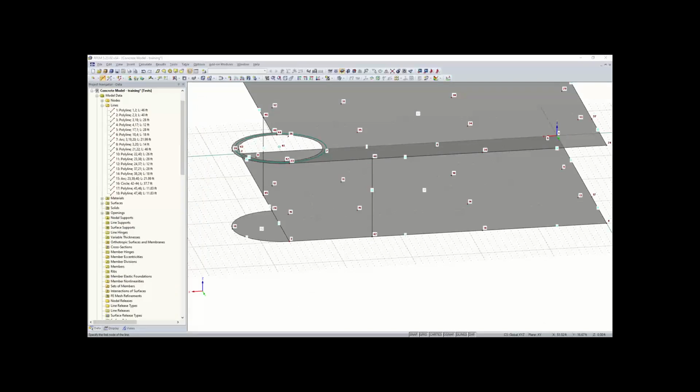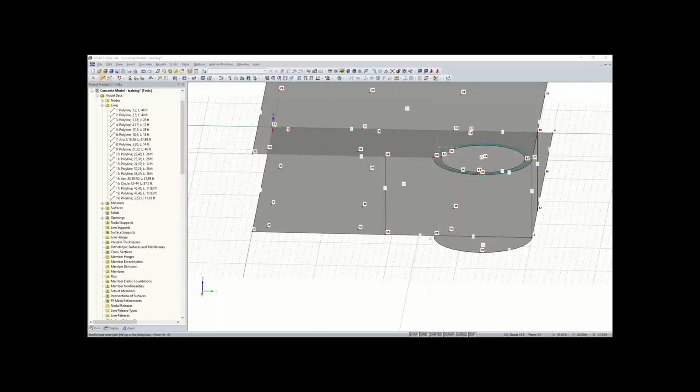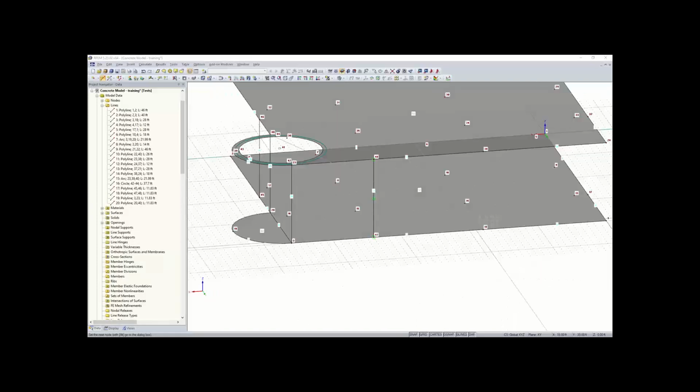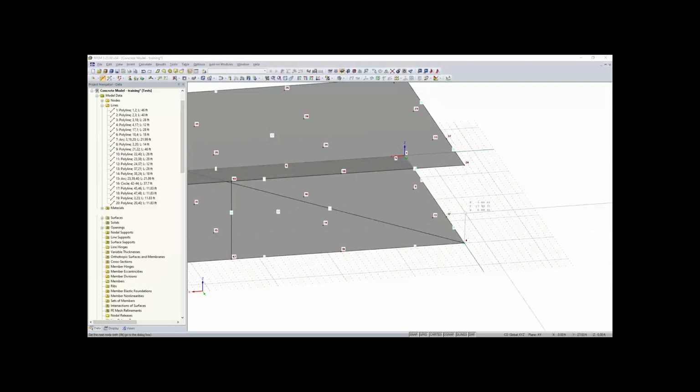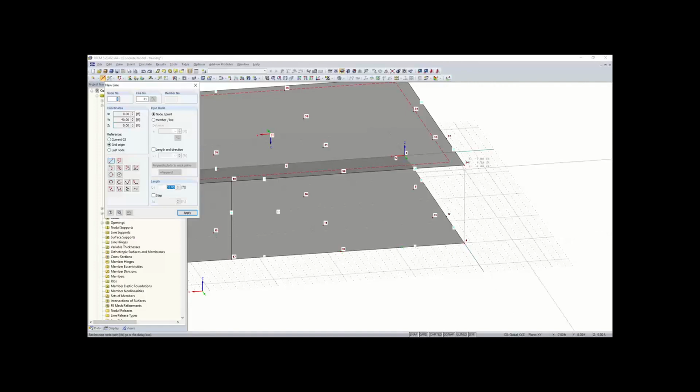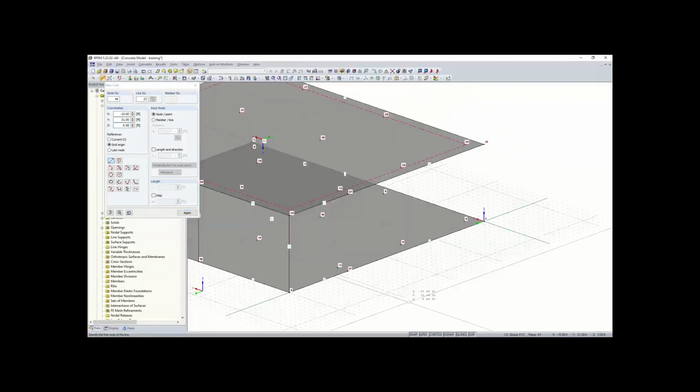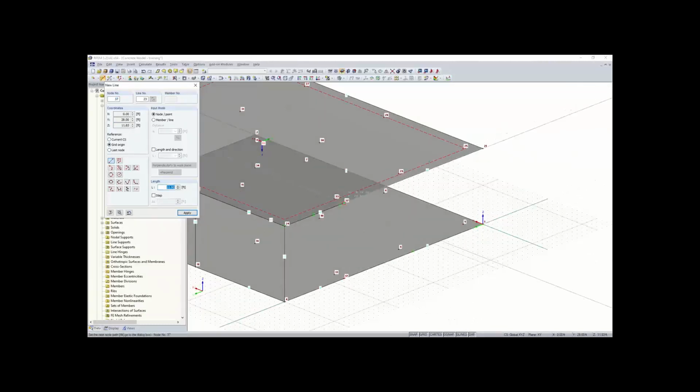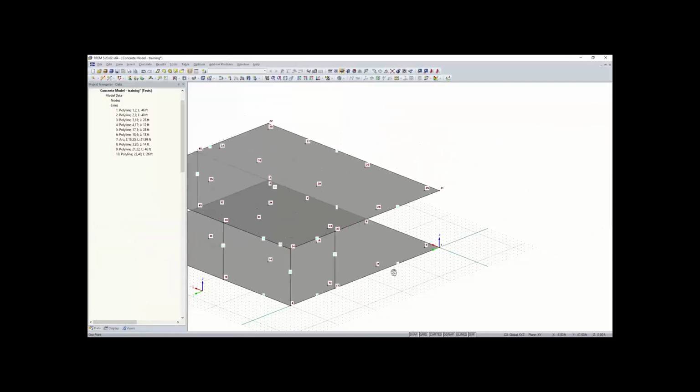And now we can simply connect the rest of our nodes here, we don't have to create any more nodes. So 3 and 23. Let's see, 20 and 40. What else? 4 and 24. Oops. Looks like I created a line there. Control Z. I can go back up to new line and just connect 4 and 24. And then we also want to connect 18 and 38. And also 17 and 37 here. And again, these are just creating our boundaries for our walls.